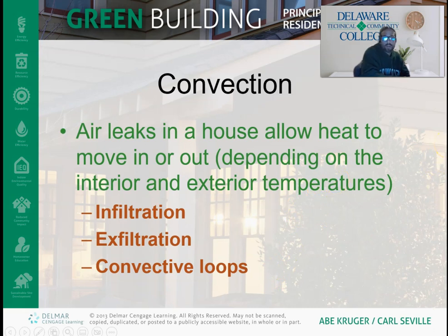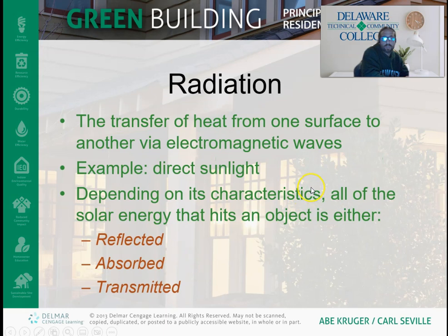And convection is important. We'll talk about this in more detail when we talk about the stack effect and ventilation. So when you force air into a building, an equal amount of air must go out of a building. And we'll talk about that implication throughout one of the lessons.